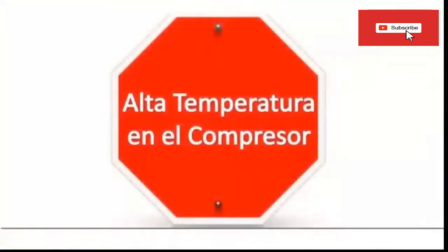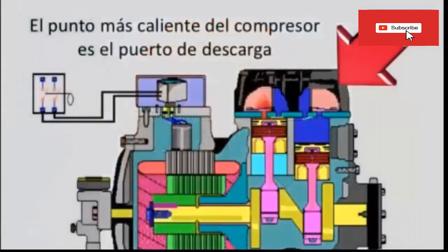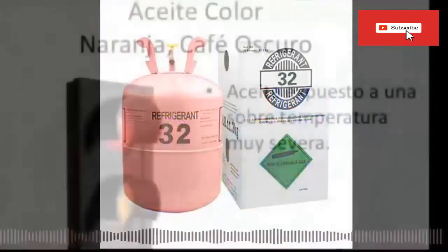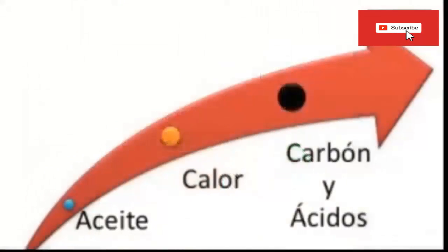I'm talking about the discharge temperature which the refrigerant R32 has. Let us remember that the compressor discharge temperature is the most critical in the refrigeration cycle, as it is the highest temperature in the system, and must always be within the ranges that the equipment compressor and its lubricating oil admit. This value is higher than the condenser temperature because the refrigerant R32 is in a superheated vapor state.